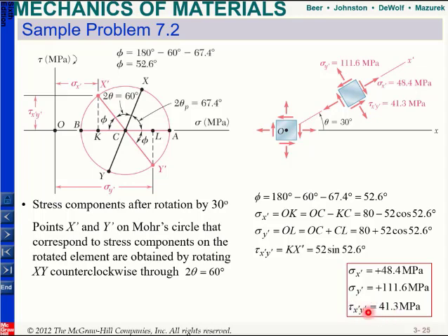And again, you should have a minus here, because the coordinates of this x prime will be sigma x and minus tau xy. Since this value is positive, your tau xy should go in the other direction. So if you plot it, this is my sigma x, and my shear should be in the minus direction, and this is your sigma y.